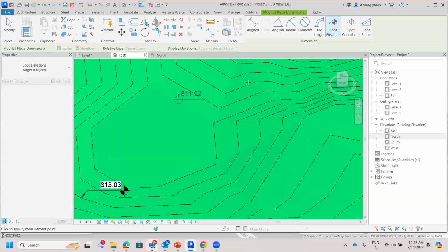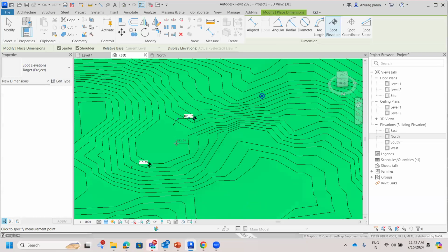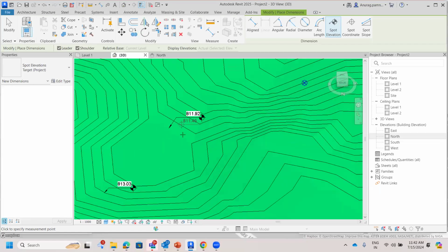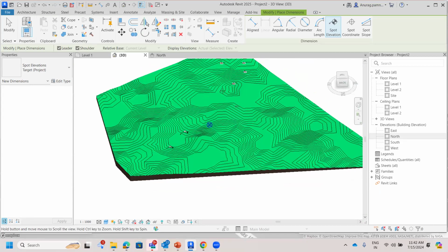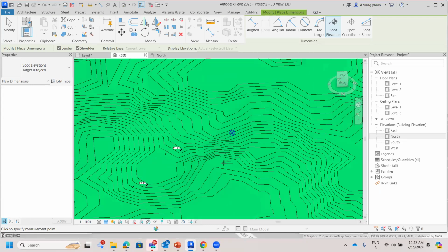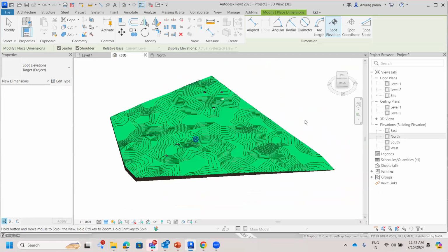So now you have acquired those particular coordinates based on the CAD file, and you have established your base point with these elevations. And now, similarly as we started with walls and pads, you can develop those things and start working within these topo solids, deciding where to grade it out and where to fill. You can decide all those things accordingly. So this is how the acquire coordinate system works within Revit.